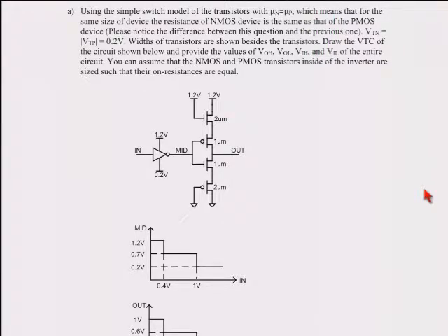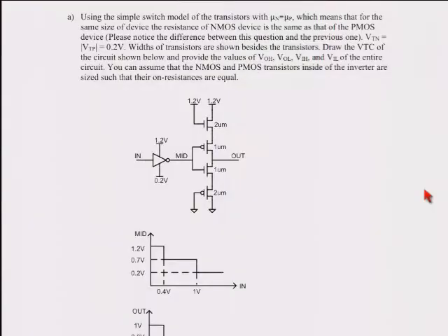Why do we have a plateau for that middle operation? You wouldn't really, it's an approximation. Remember the switch model? Assume that both transistors are on at the same time. You get a resistive divider. And a resistive divider will basically make both of them equal strength. It brings you to the VM point. In reality, it will be something like this. Right? And there's no real problem if you showed something of this nature too.